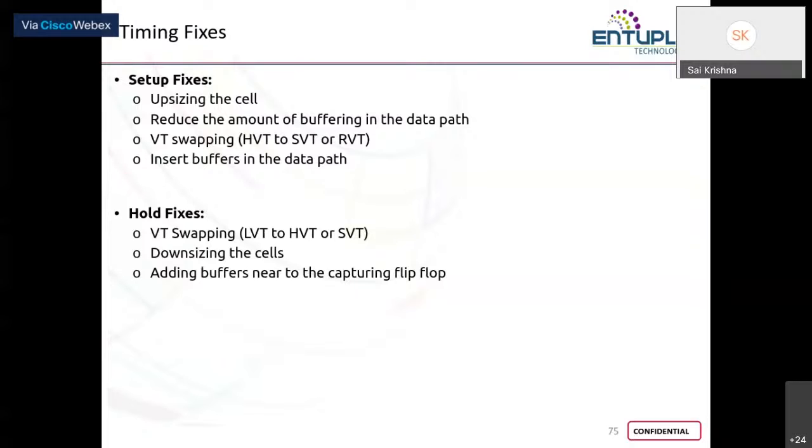For the flip flops to capture your data for setup, because it has to arrive quicker, you're pushing it harder. But for hold, you have to slow it down. And when it comes to VT swapping, you need standard or higher voltage thresholds, because quicker switching means the next data will be taken in easily, because of which the current data may not be handled properly.